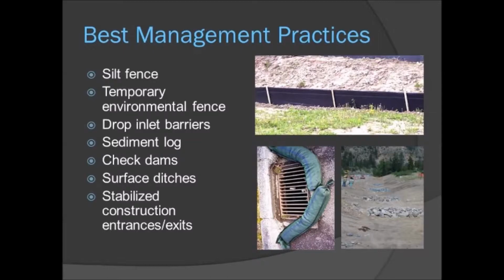BMPs, or Best Management Practices, are tools that are used in sediment control. Some of the most widely used BMPs are silt fence, earth berms, drop inlet barriers, check dams, and stabilized construction entrances. While working in the field, be conscious of these BMPs and take care not to damage or dislodge them. If you do damage any of these BMPs, please notify the ECS.